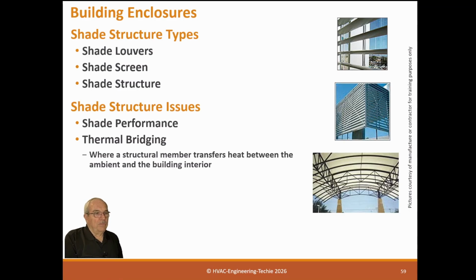And when you thermal image a building, if you have thermal bridging, it shows up right away. So you can see this. So shading structures are designed to improve the thermal transmission of a building, so they are important to us. Normally beams, trusses, and other structures are part of this thermal bridging.